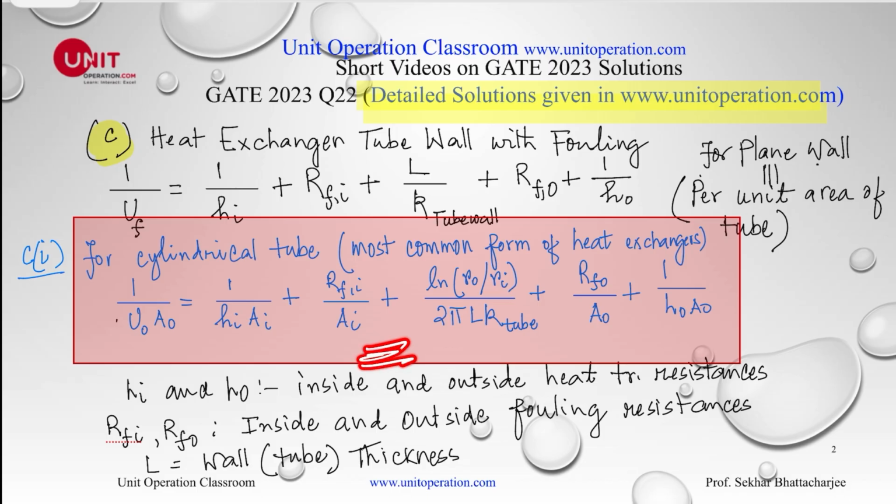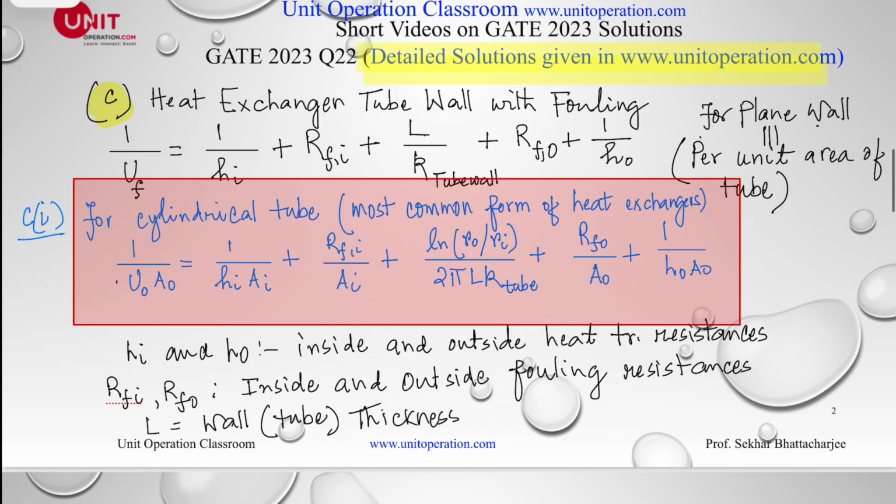So here, let's say this is a liquid flowing through it, and this is the thickness of the wall of, let's say, a steel tube. So here there is an inside thermal resistance, the resistance to flow through this tube, and of course then the resistance to flow outside of the tube, and there is fouling here and there is fouling here. So basically there are inside and outside fouling resistances. Okay, so you add up all the resistances. These are resistances added in series.